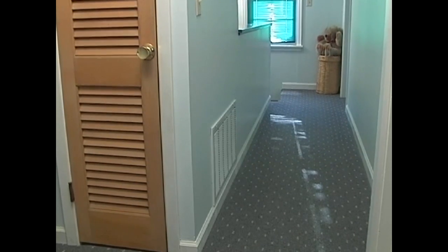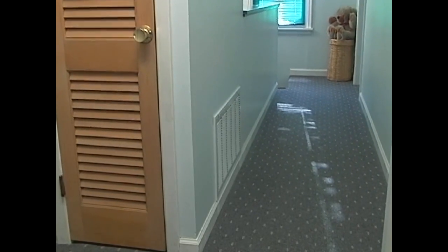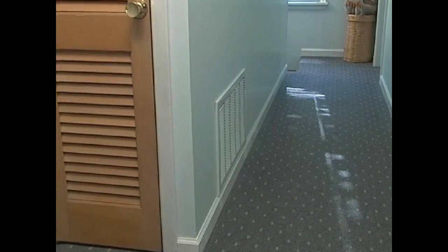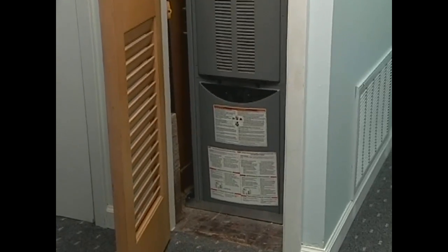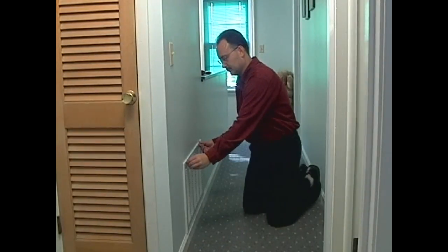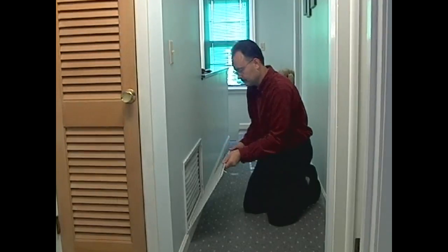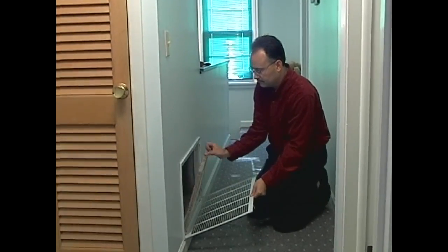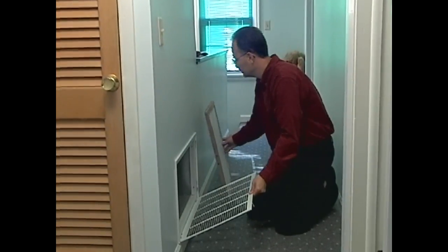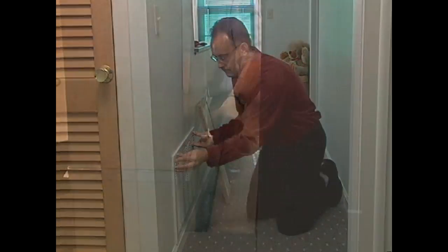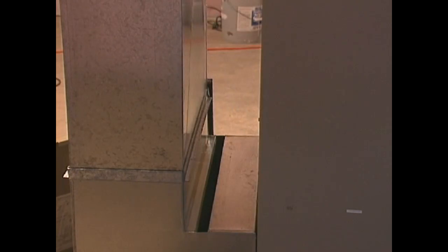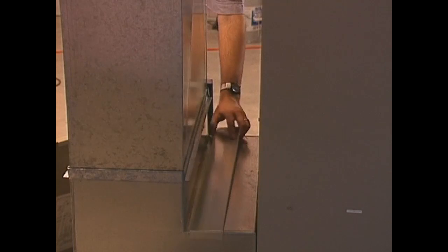The first thing we need to do is connect the duct blaster fan to the duct system. This is typically done at either a central return or the air handler cabinet using the blower compartment access panel. For this test, we're going to use the central return as the location to connect the duct blaster fan. Check the central return to see if there's a filter mounted on the filter grill on the back side, and if there is, remove it. In addition, if there are filters located at the air handler itself, these will also need to be removed before we can begin.